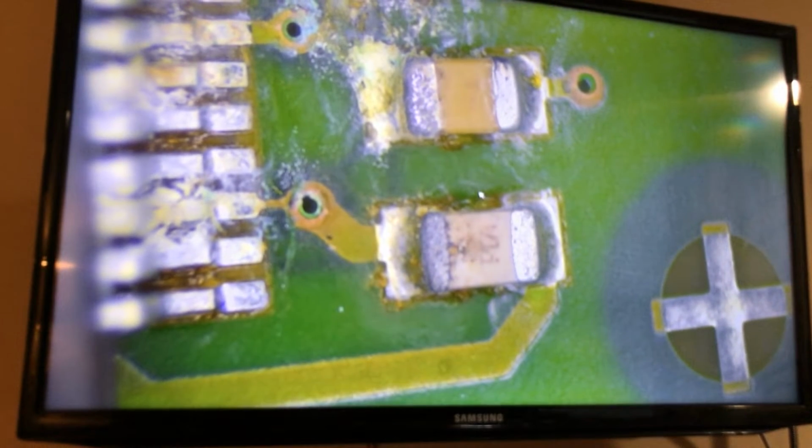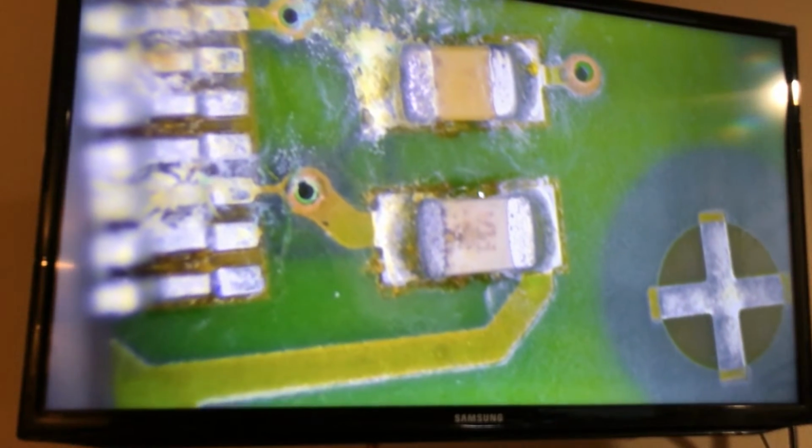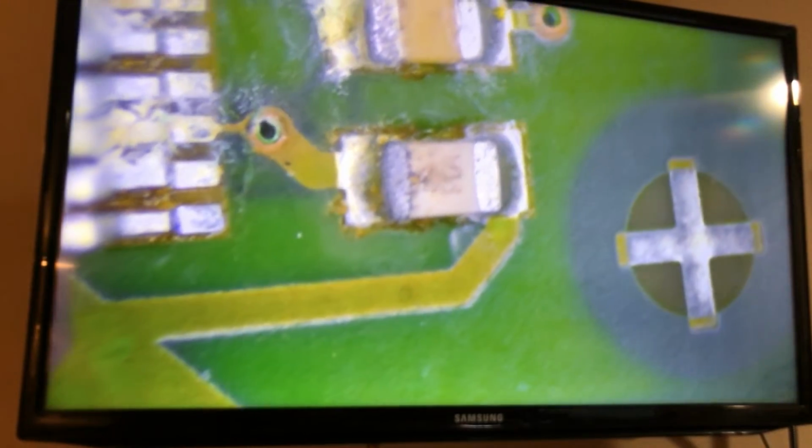The only way I can check the capacitors is if it is removed from the board. So what I would do is probably remove this one and compare the readings to the one next to it. This one had some sort of a reading on it. These legs in here are really, really bad, at least that's what I can see with all this dirtiness.